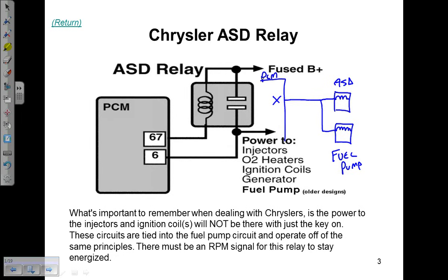So what you'd have is maybe the fuel pump and the fuel injectors together over here, have the fuel pump and injectors, and on this relay you'd have your coil, your O2, and your alternator. So basically they separated the loads, but if you look at the circuit design, I'm not drawing all of it, there was only one driver. So when this circuit turned on and was given a ground, both relays were energized together, and so essentially you still have the same thing. You have the same characteristics. If you lose a crank signal on this system, you're not going to have power to an ignition coil.